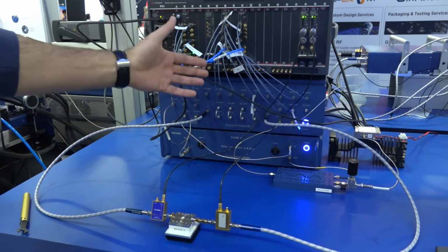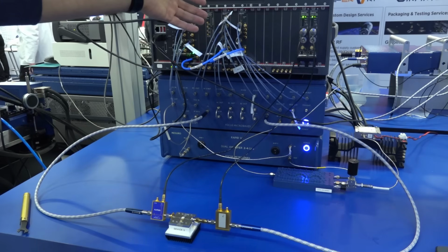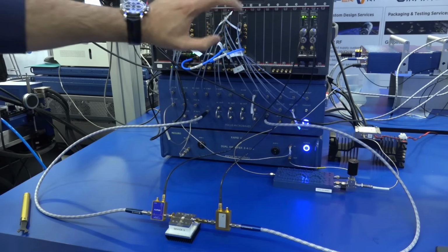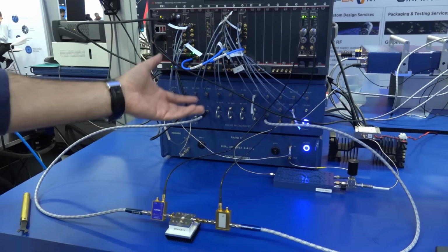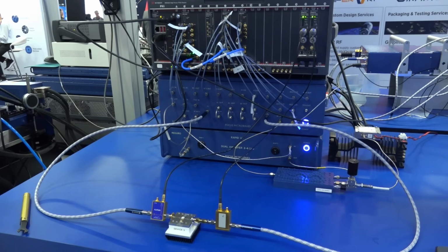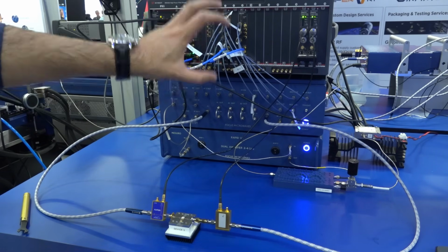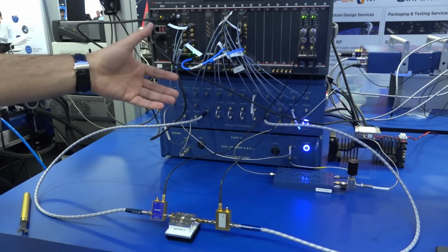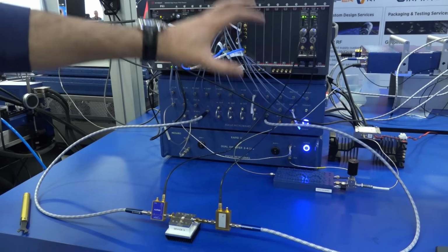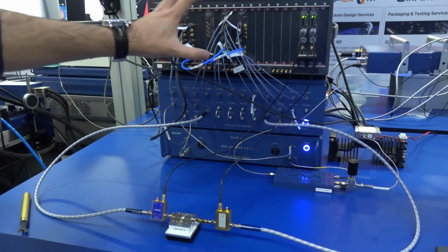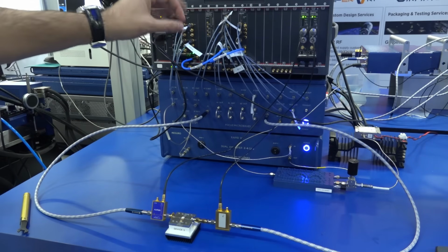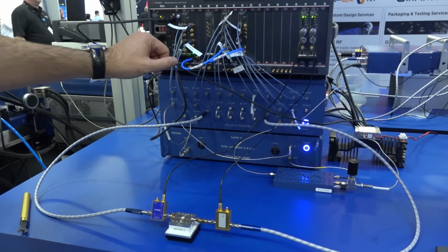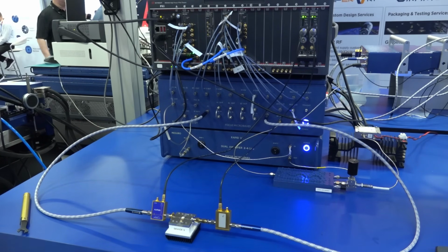And that signal is coming back from that box going to direct digitizers. So basically, you're doing a complete analysis by exciting coherently the input and the output and synthesizing all these complex modulations. Now, imagine how many other things you can do once you run these correlations. So for example, you can almost emulate the entire Smith chart, so you're covering the entire load pull system. You can do this at the fundamental and even at the second harmonic to get that little bit of a return that you want on that. Remember, this is running completely on modulated signals.